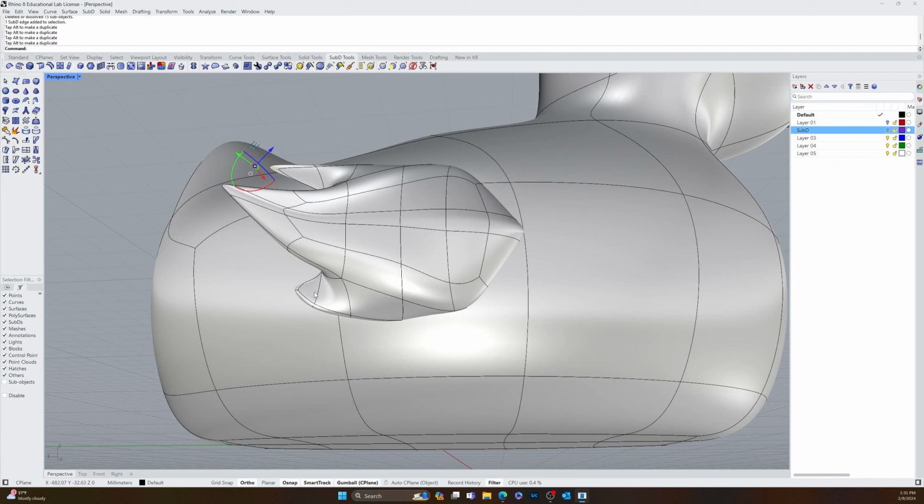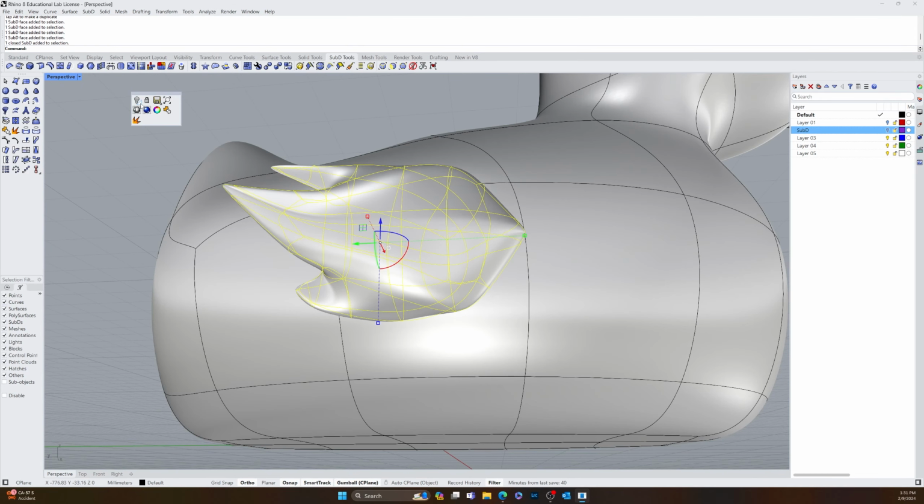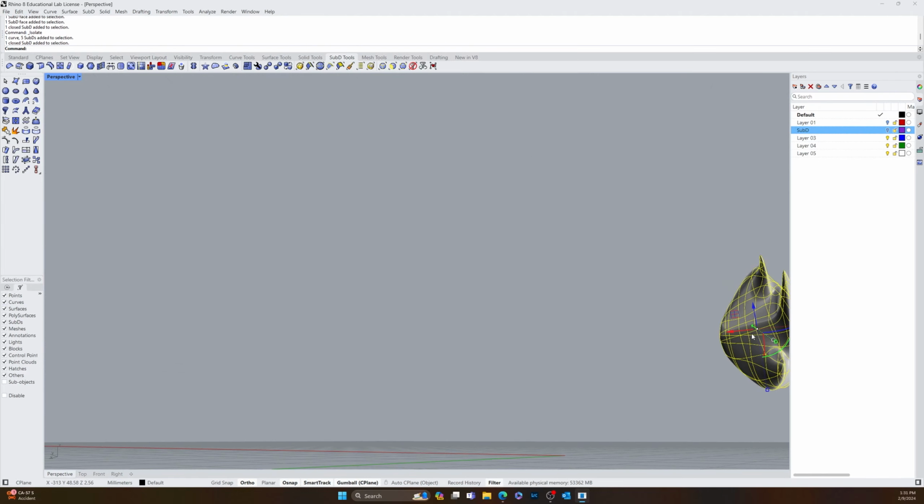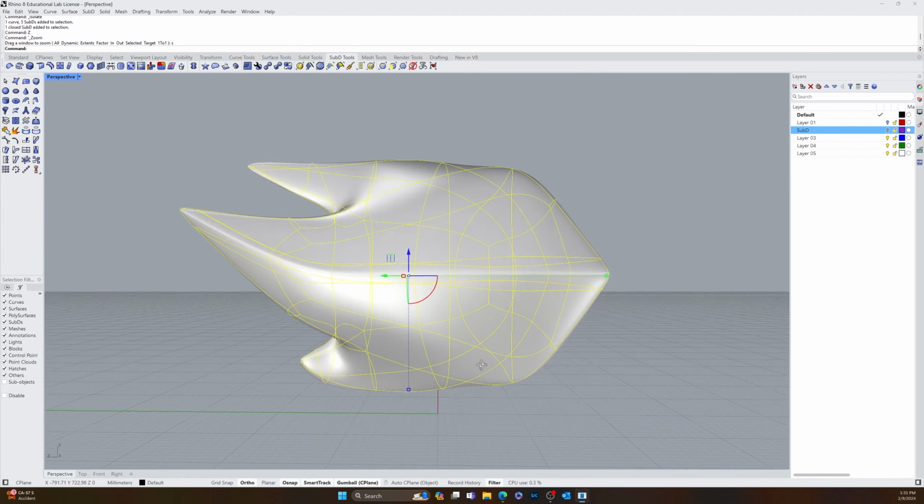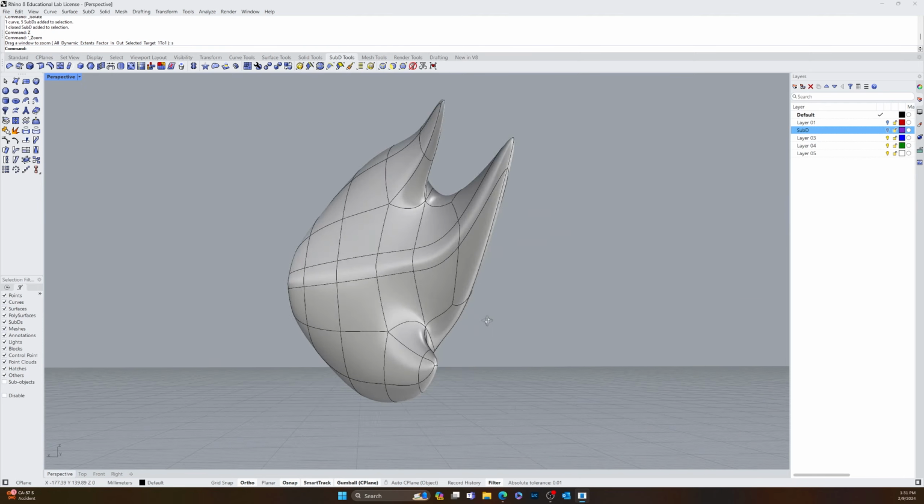And then I actually don't want any of this stuff underneath. I almost want it just to be that one side. So let me isolate this. I can click on the center mouse wheel, hold down this, and hold down the left click button, and then go to this one right here, isolate. So Z enter, S enter. So I'm focusing on just working on this.